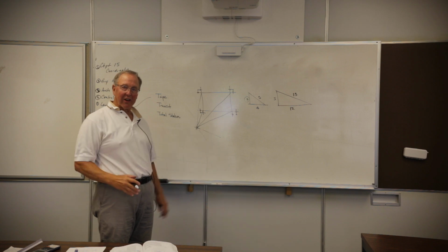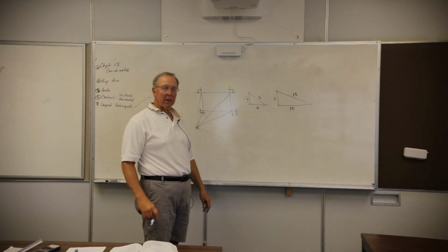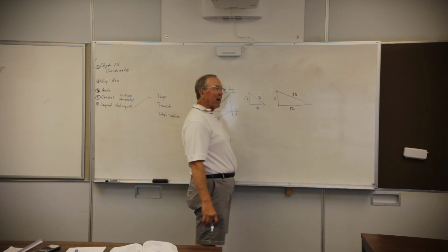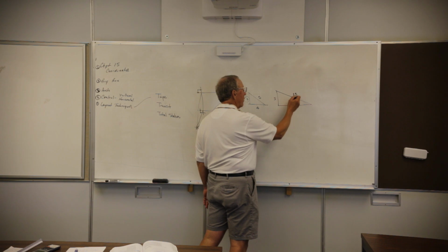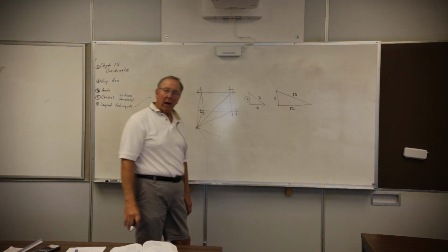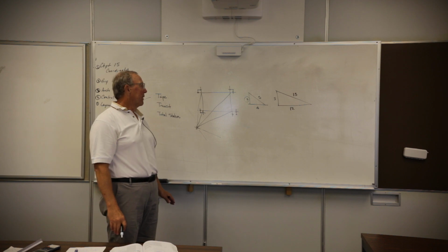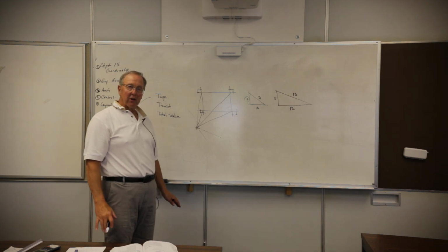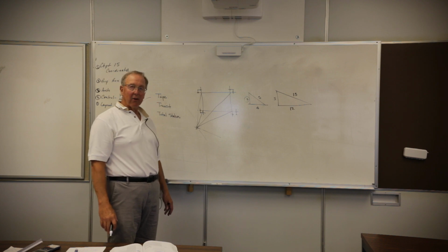So if I've got a long, skinny building, I wouldn't use the 3, 4, 5 triangle because those sides are pretty close. I would use the 5, 12, 13 triangle. And once again, all we do is multiply. If I've got a 20-foot wide building, multiply this by 20, that'd be 48 and 52. I've got my dimensions, and now all I do is cross the tape and make sure that those three sides coexist in the right proportion, and I've got it laid out.